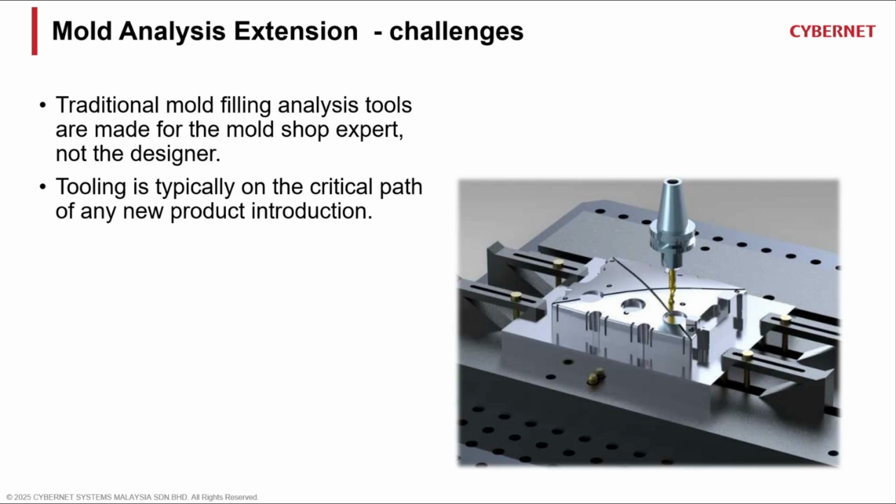If there is any problem here, it gets really expensive, because you have already built a mold base, but the mold coming out of it may have air traps inside and some aesthetic problem causing the appearance not to look good. So it costs even more and delays your product to market.